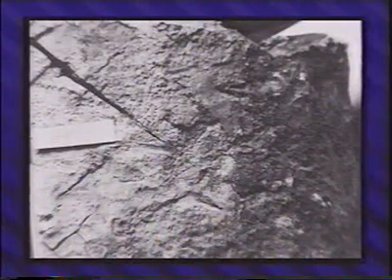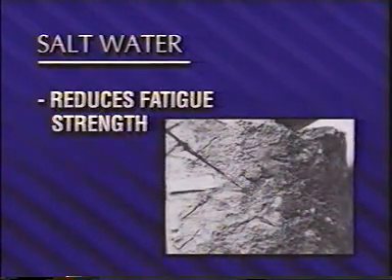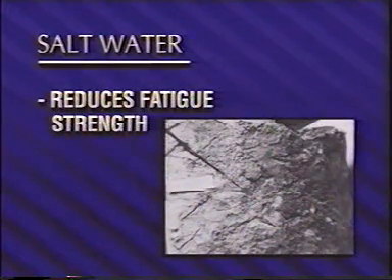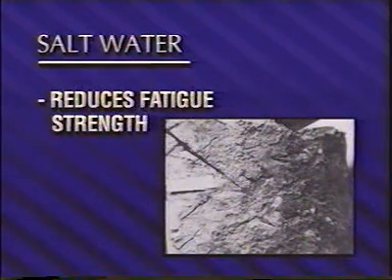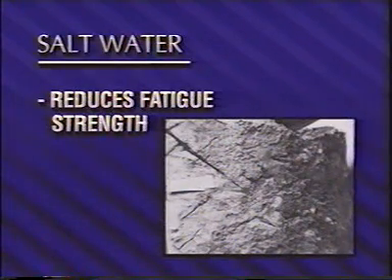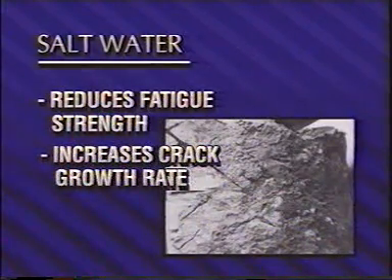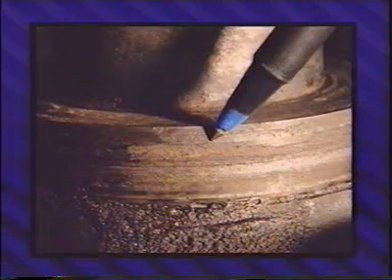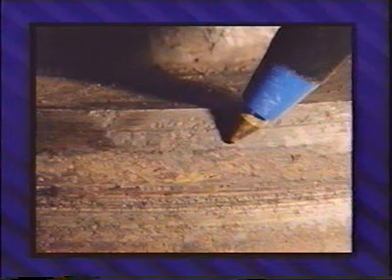Corrosion fatigue tests on smooth specimens of high-strength steel indicate that very large reductions in fatigue strength or fatigue life can occur in salt water. For instance, the fatigue strength at 10 million cycles could be reduced to as little as 10% of the fatigue strength in dry air. In these tests, the main role of the environment was corrosive attack of the polished surface, creating local stress raisers that initiated fatigue cracks. Salt water also increases the crack growth rate in steels, provided the cyclic rate is 6 cycles per second or slower.